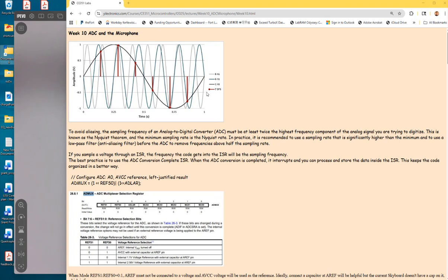Knowing that VLSI level of the ADC will be very beneficial because one of the registers is controlling the ADC's clock rate. If you don't know what's going on for the clock rate of the SAR block, and you are doing a quiz just after this class for the VLSI class on the SAR, okay? Down to the transistor level, you know how that clock is actually being used for the SAR, which is very helpful because you will know that if there are 10 bits, it takes more than 10 cycles. It could be 13, could be more, depending on how they design it.